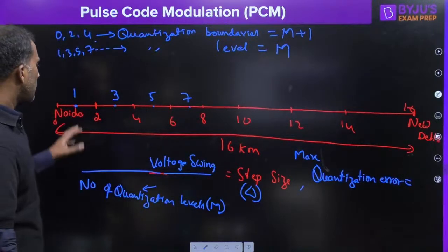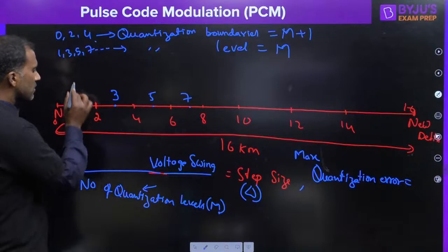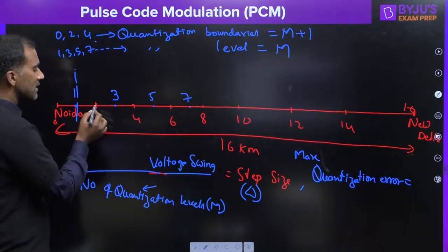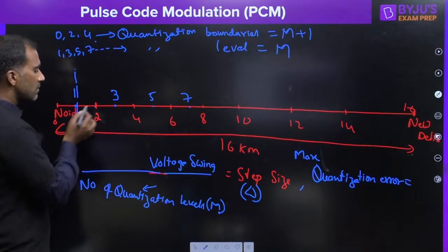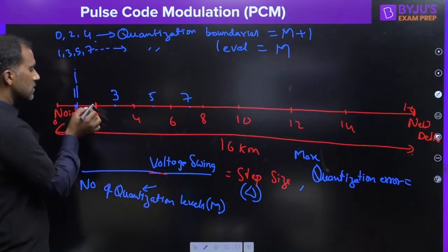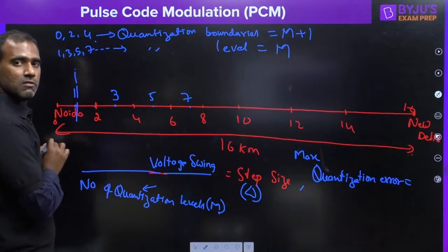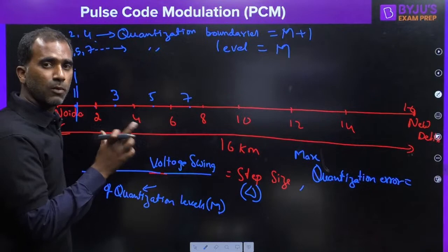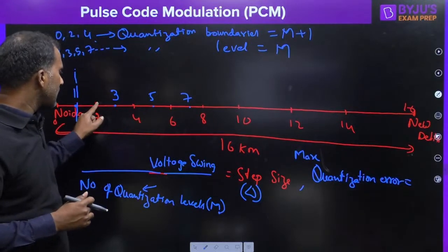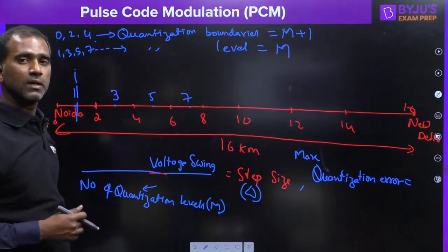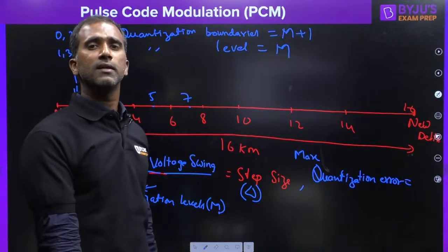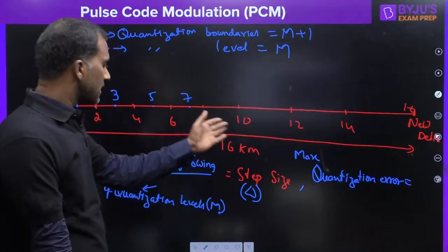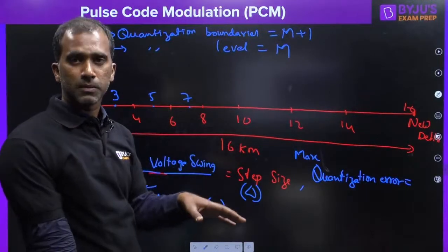Next, how about maximum error? If the signal is taking 1.9 volts, but the closest level possible is 1, the quantization will be 1. 1.9 volts, when you pass it through the quantizer, will become 1. The maximum error possible is 0.9. For 1.9999, the closest level is still 1, so the error is 0.9999, something like 1 volt. In this design, more than 1 volt is not possible.